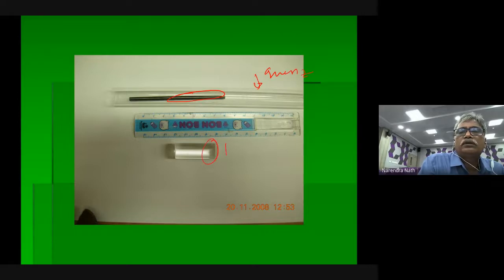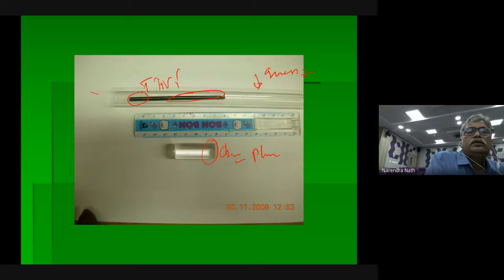This is the quartz plug. This is titanium nickel. Here you place it inside. This is actually a rod I placed. If you want, you can put a plate also, if you have a big quartz tube. Before placing, you have to get a vacuum inside. You connect the tube chamber to a vacuum pump and suck out all the atmospheric air. Then you place it.